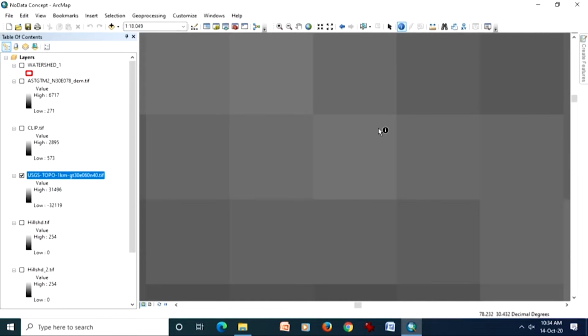The pixel value is the real elevation value, which is what is useful. You also might be knowing this, and it will also come in future discussion, but since we are having a demonstration, I will briefly touch on this USGS topo. This USGS topo global digital elevation model has been developed employing 250,000 survey topo sheets of various countries, and the contours from these 250,000 scale topo sheets have been digitized, and employing interpolation techniques, a global surface has been created at 1 kilometer resolution.